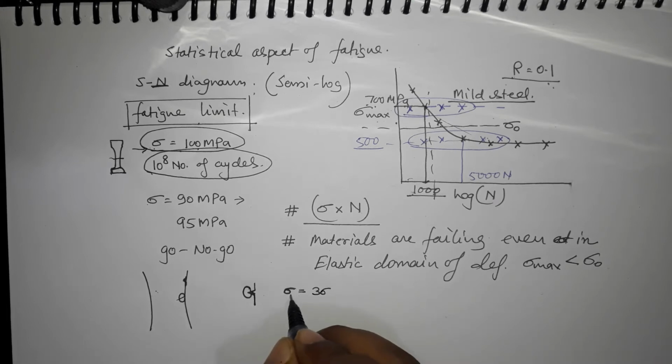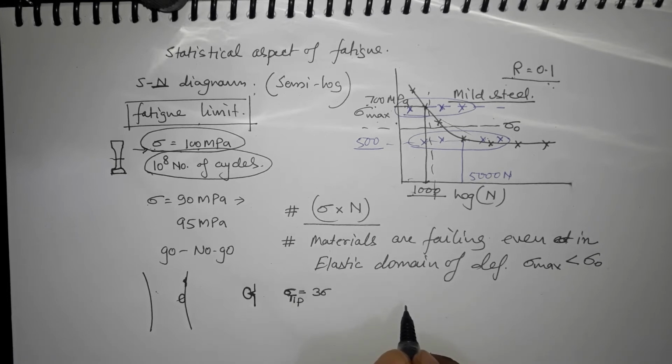Okay, so at the tip you can have stresses more than 3 times higher than what you have applied, and this we can get from the expression of stress concentration factor, right?